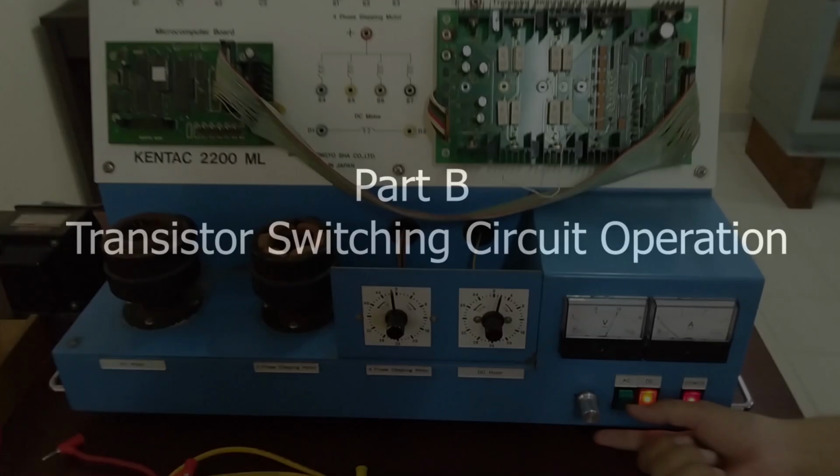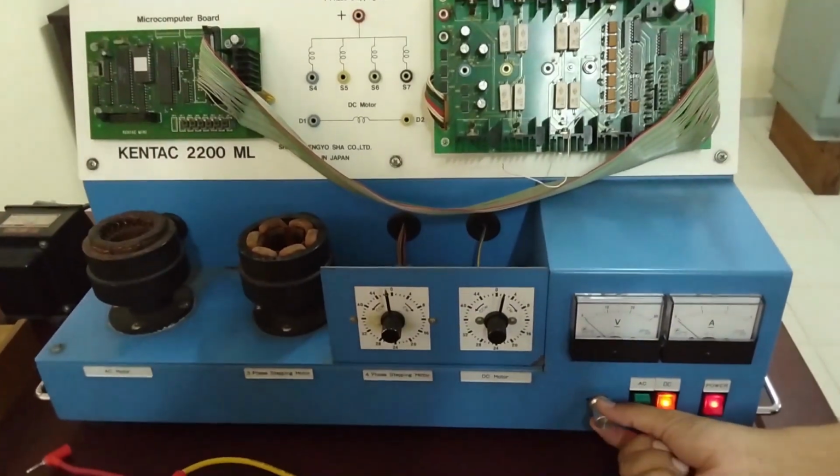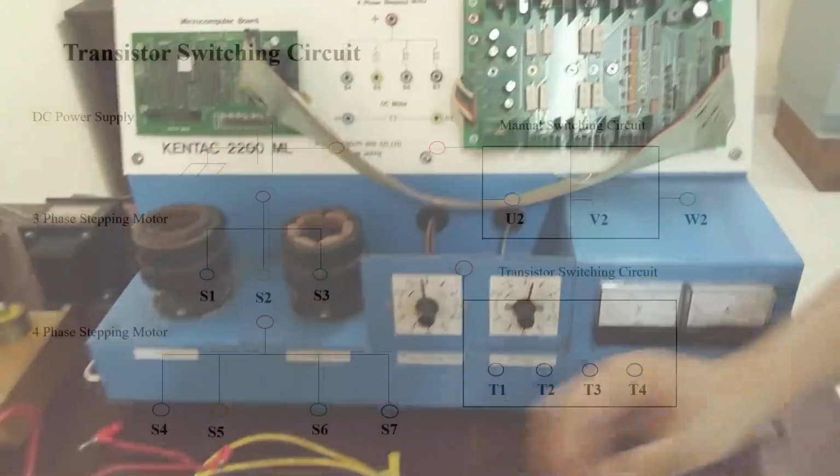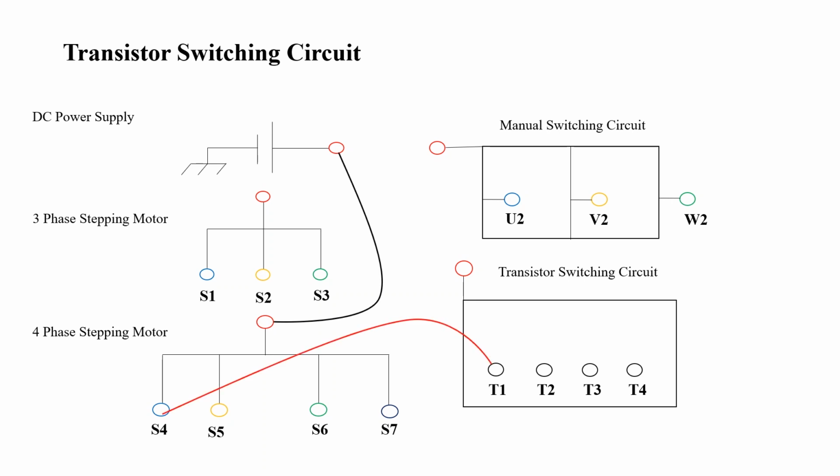Now, let's move on to part B of the procedure, transistor switching circuit operation. First of all, we have to set the voltage regulator dial to its minimum position and also switch off all the main switches. Now, let's see how the terminals of the 4-phase stepper motor are connected to the transistor switching circuit. First, connect the DC power supply as shown here, and then connect the terminals of the 4-phase stepper motor S4, S5, S6 and S7 to T1, T2, T3 and T4 of the transistor switching circuit respectively.